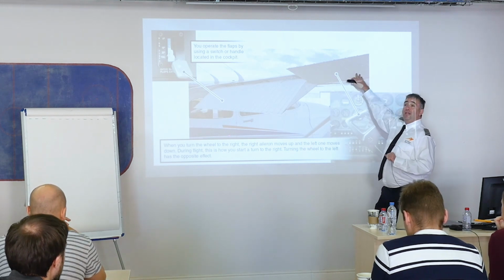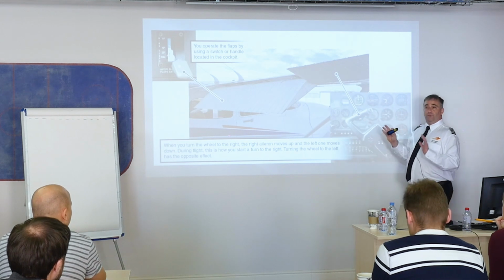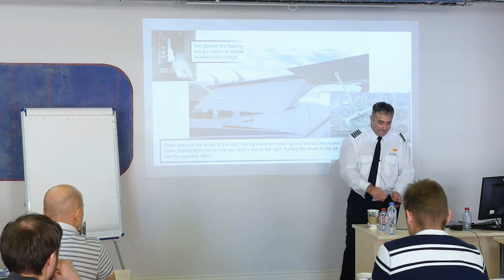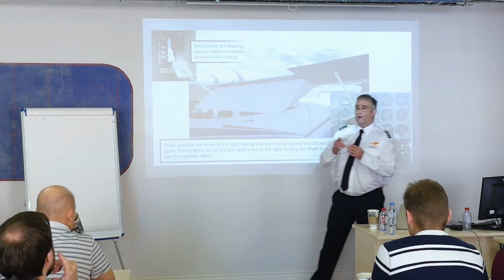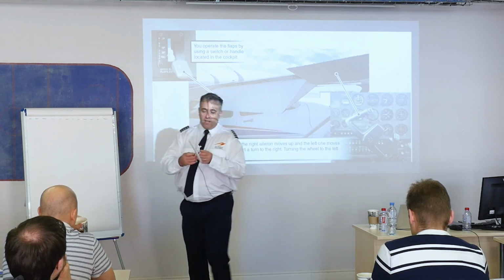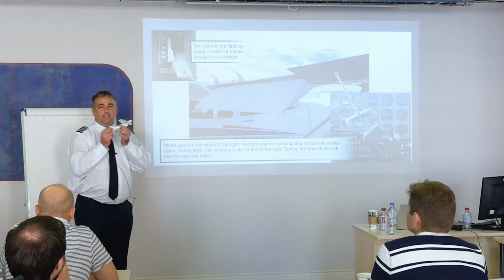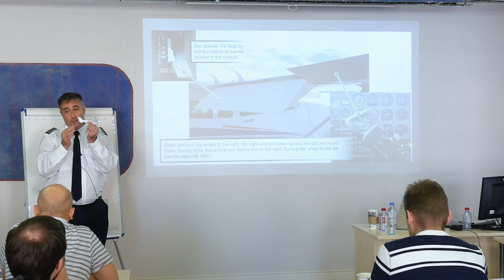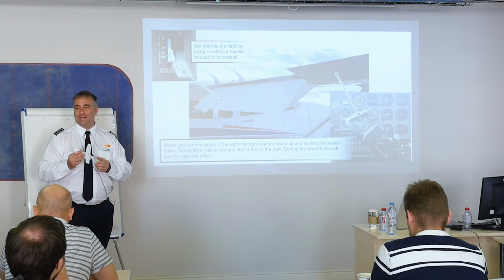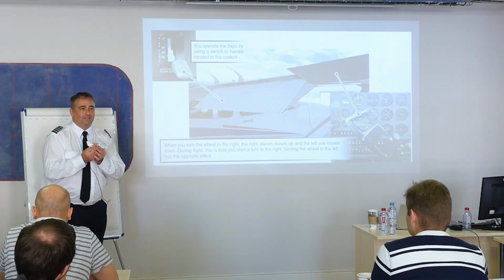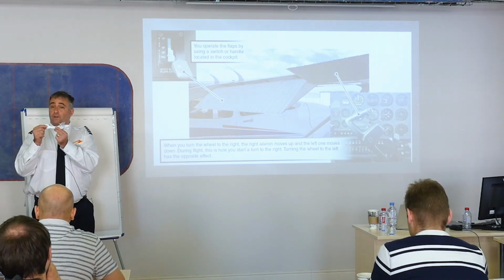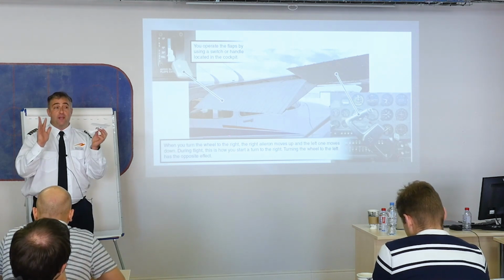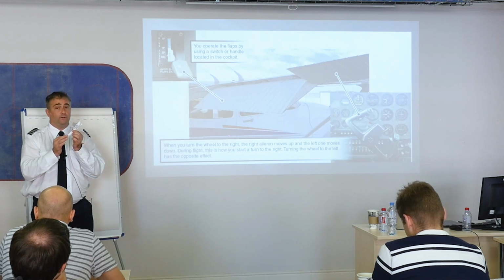All right, because the ailerons are on the outside of the wing, and it's important that I know flap, aileron, that's easy, but where are they at? They're built that way for a reason. And the reason is because the airplane is able to fly at cruise speed, relatively fast. Well, we could say relatively fast, 120, all right. Cruise speed, or I could fly it very slow. I could fly somewhere around 35, 40 knots, right? Very, very slow.